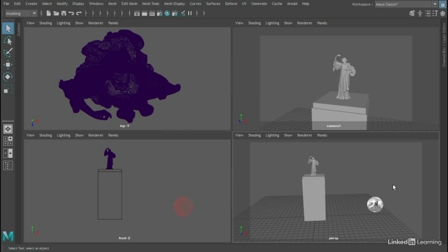And to do that, I've positioned the Sky Dome light where it will not be visible in the viewport. If I zoom in on my figure of a dancer here, I won't see that distracting image in the viewport. That's because we actually cannot turn off the shading of this Sky Dome. The only way we can get rid of that shading is to set the viewport to wireframe. At least in Maya 2020, an Arnold Sky Dome can never be displayed as wireframe in a shaded viewport. The usual methods of template, reference, and drawing overrides don't work. And if we don't want to see the environment backdrop in the viewport, the only option is to push the light object somewhere off screen.